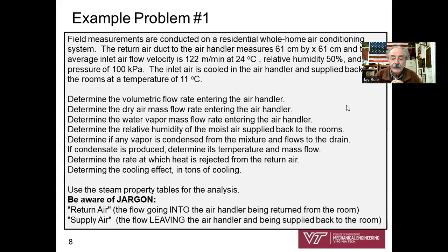Measured it myself. And coming back at 24 degrees C and a relative humidity of 50%. That's very typical of the summer. And the system pressure here in Daleville, atmospheric pressure about 100 kPa. Okay. The inlet air then is cooled down in the air handler and supplied back to the rooms at a temperature of 11 degrees C. So that's very typical.